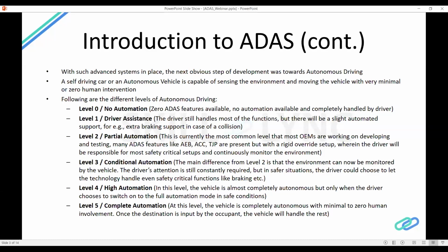As usual, when coming to eyes on and hands on, both can become eyes off and hands off if the driver decides. If you're following the flow, I hope I'm not confusing. Level 0 is eyes on and hands on, meaning eyes always on, hands always on the steering wheel. Level 1 is again eyes on and hands on. Level 2 is eyes on and hands on, but hands can be off if the driver decides. And level 3 is eyes on and hands on, but both eyes and hands can be off if the driver decides. So I hope you're seeing how the levels are developed.